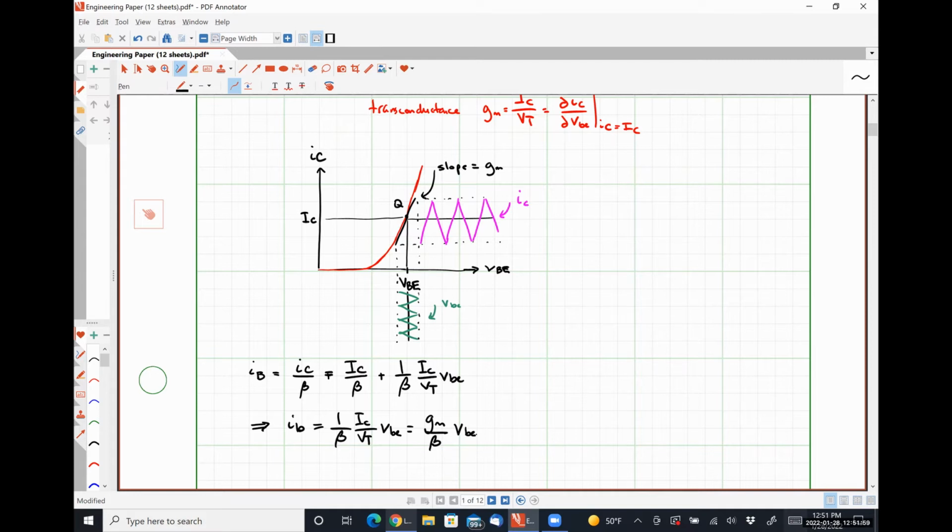And so I want to stop here and talk for just a second. For our large signal model for our BJT, what did we see between the base and the emitter when our device was operating in the active region, the forward active region specifically? You guys have notebooks. You presumably have been taking notes in this class for at least 6 weeks at this point. Large signal model of a BJT. I literally just gave you the answer. It's a diode, yes.